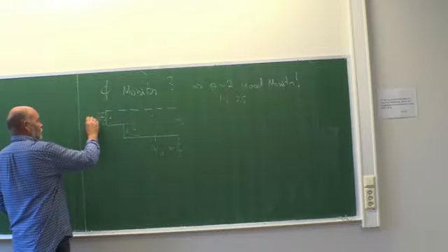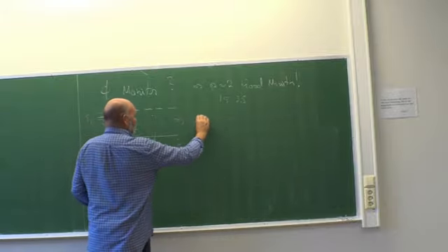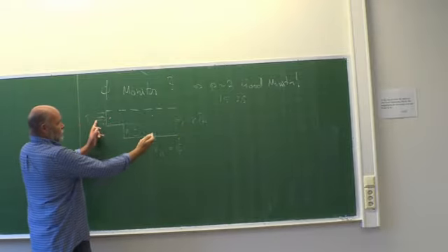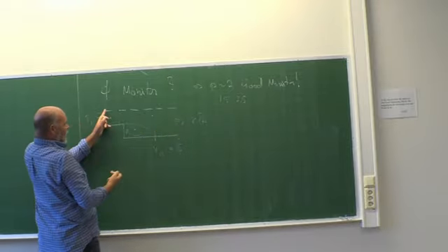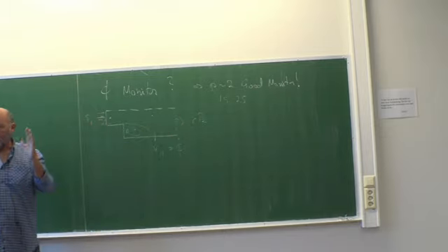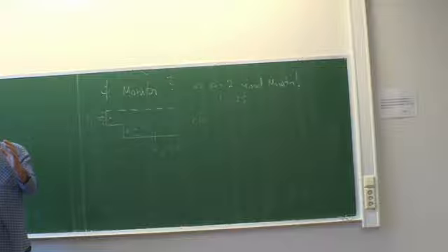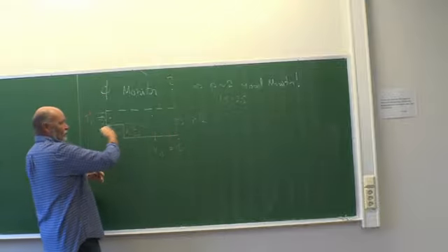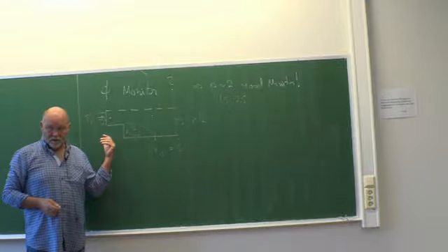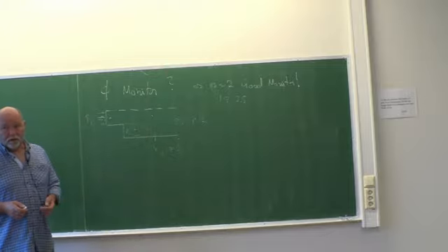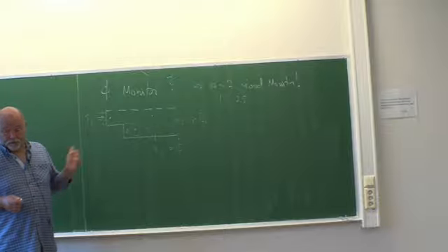Clearly that's going to be the difference between the 2 pressures. So you could have used the pressure difference, an average pressure here versus the average pressure at the outlet. That's a driving force in the problem. Of course, that's also sensitive, because this driving force has to balance all the resistance inside the computational domain. So that might also be a good monitor. I haven't tried it, but